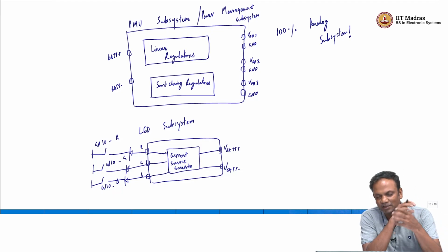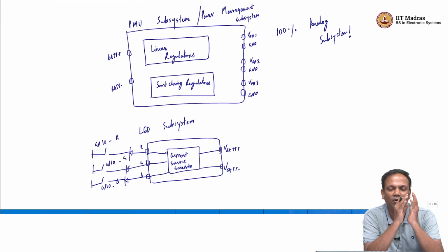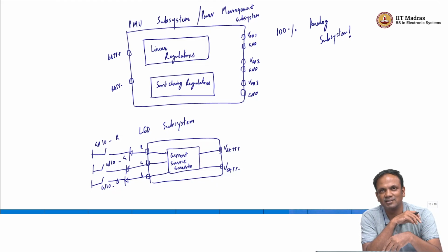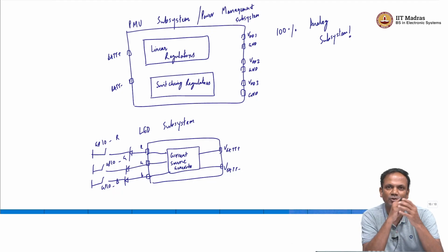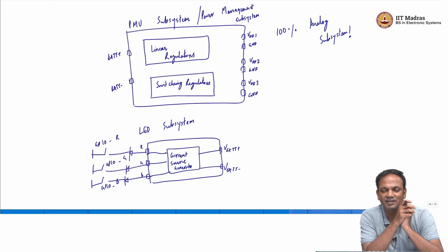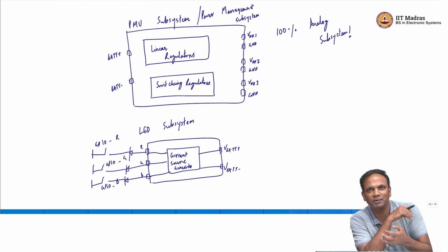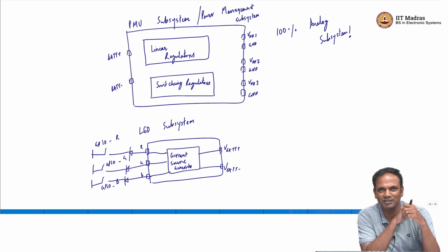Now, you can say okay, whatever be the battery voltage, I want that light intensity to stay exactly the same. One way to achieve that is by ensuring that the current source is independent of the battery voltage. So, it is pretty close to an ideal current source, which means that it also needs to be designed to ensure that the amount of dependence on VBAT is very, very small. That is possible to do, depending on how much importance you place on these things.